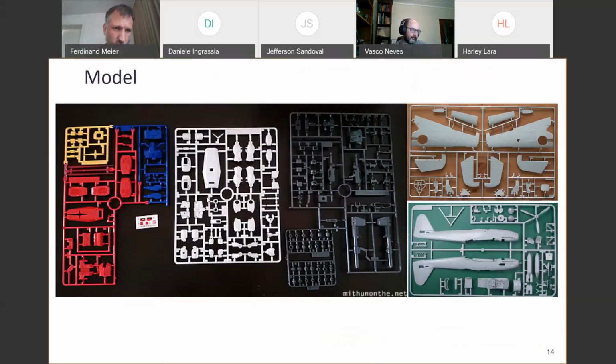Those pieces are very similar to what we're doing. In this case, it's plastic injection molding, but the principles are the same. So you have your sprue, which is probably somewhere here. Then you have the runners, which are those, and then the gates, which are these. Actually, you don't really see it, but there's a tiny little connection that connects your pieces to your part.